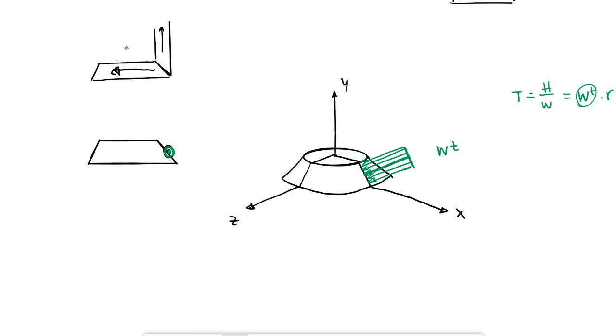So if I do this correctly, I would be able to get all the dimensions for this. So I can see something like this, something like this, and I would have a bevel gear that actually looks like this, right? This angle, gamma, can easily be found because I have, for example, the radius of this gear if I have the diametral pitch, and the radius of this gear if I have the diametral pitch.